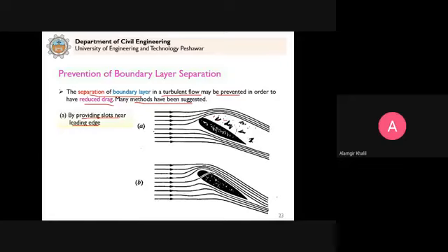and it will increase the drag force. You earlier saw in the video also. But if we provide slot holes here in the entire length of this body, you can see here that by providing these slots, the boundary layer separation is avoided.